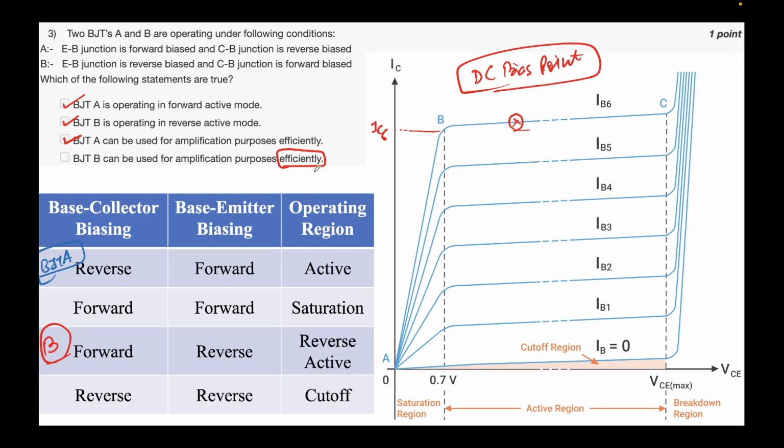As I've been saying, let's say this is an NPN, this is N plus, P and N. You can see that the base will remain the same. If I switch the roles of emitter and collector, how is it going to change? The doping is the thing that is different. And I also told you the area is different. The collector has a wider area for heat dissipation. So even if I switch the roles of emitter and collector, reversing them, it is still technically an NPN BJT. The problem is that the efficiency reduces.